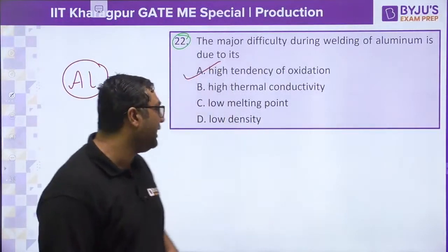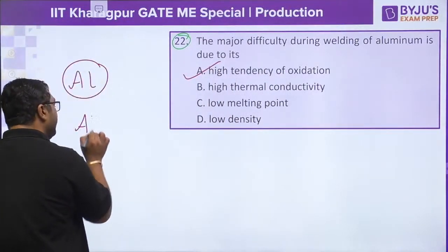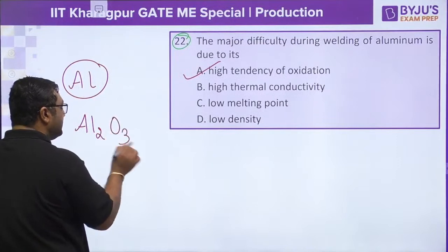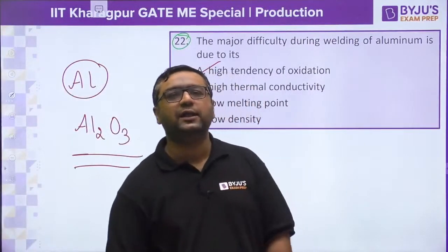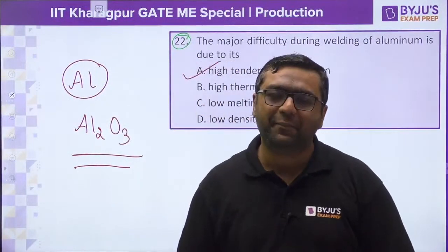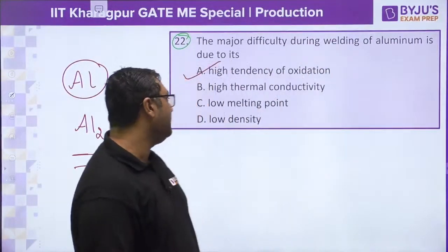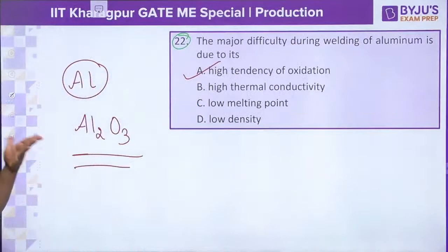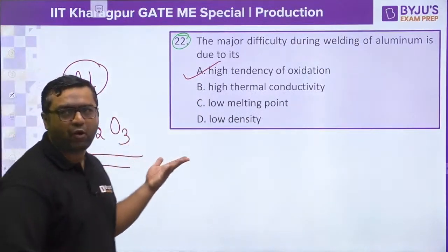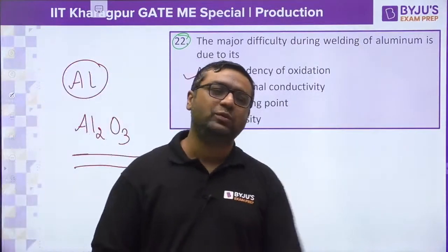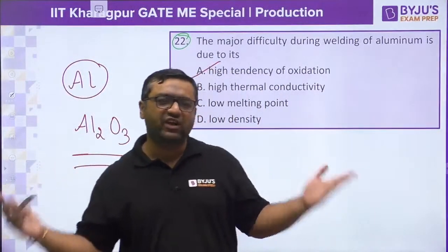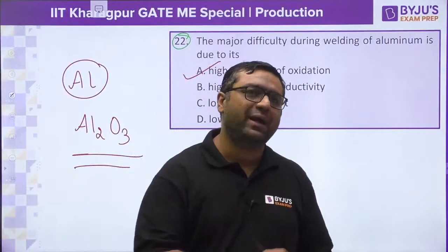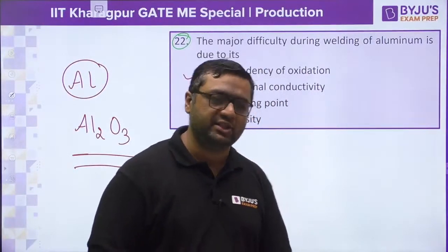So my dear, these oxide layers, when it becomes Al2O3, which is a ceramic ionic solid, that is that much hard material that we are even using it as an abrasive material for cutting. So my dear, this is hard and brittle. That is why it is difficult to weld upon. So always at room temperature aluminium will be found with a layer of Al2O3. So it is very difficult to weld. So we are welding it by cathodic cleaning process of TIG.